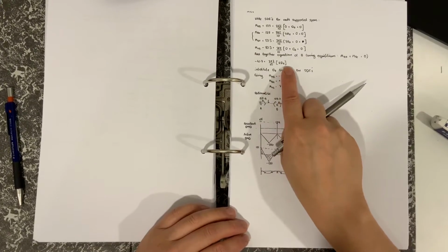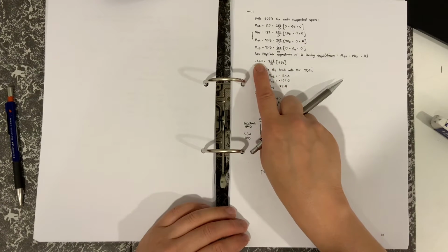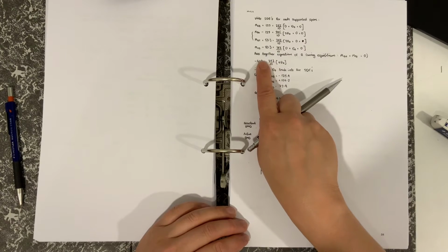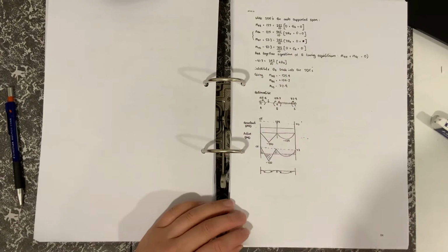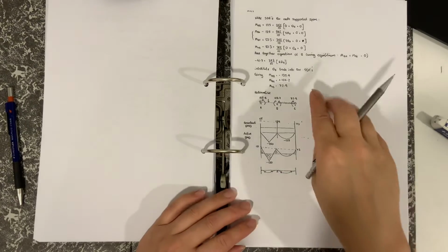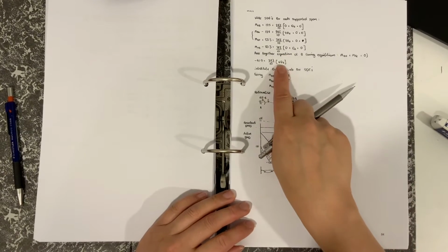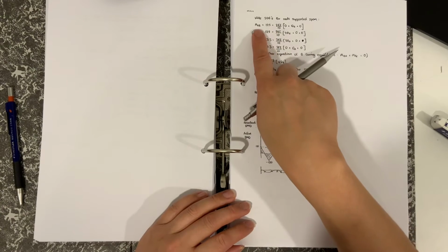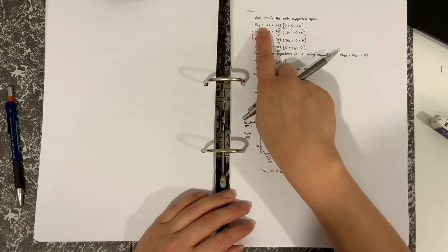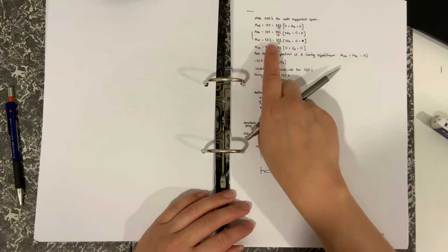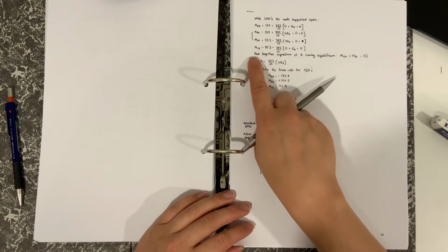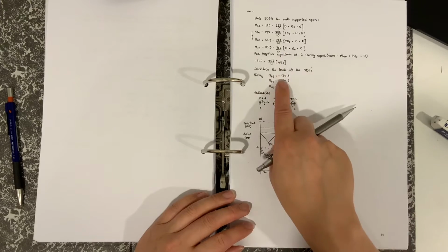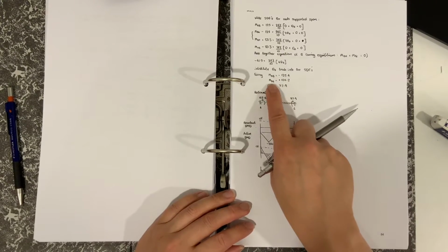Substitute from there, you can work out what theta B is. Theta B is just minus 41.7 times 10 divided by 2EI over 4. Okay, so we've got a value for theta B. Now, having a value for theta B, we can solve MAB, MBA, MBC, and MCB, and we can work out what each of these are.